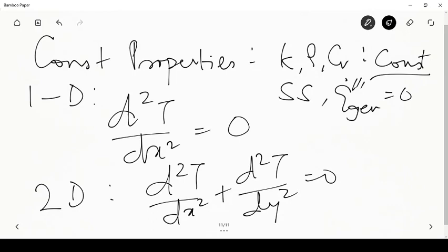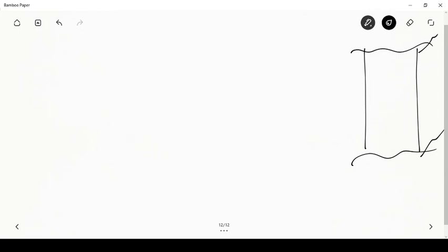So now let us try to focus on solving this equation analytically. So what are we trying to do now? We are trying to look at a simple one-dimensional wall. So it's infinite extent in this direction as well as in the depth-wise direction. So you have, this is x equal to 0 and this is, let's say, x is equal to L. Now these two walls, this left surface and the right surface, are maintained, let us say, at temperatures T1 and T2 respectively. And we would like to solve this equation and find out what the temperature distribution in this wall would look like at steady state.